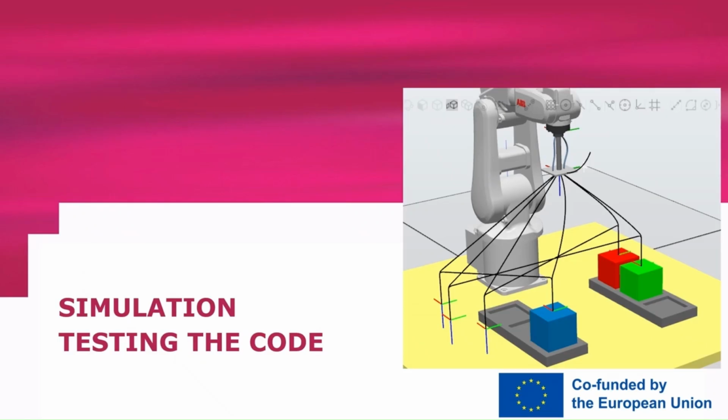So the last step is the full simulation of the robot program, which we should have now created for picking and placing the blue, red, and green boxes. As you can see, the red and blue box have changed positions, but it doesn't matter. Important is that they're in the correct order. And what we also want to do now is activate TCP monitoring, which allows us to see how the tool moves and acts in the system.